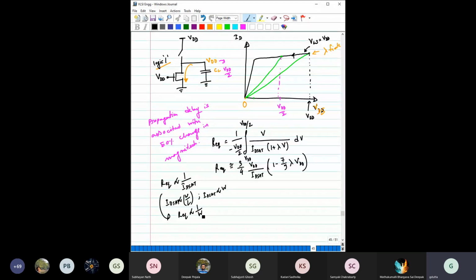So remember this relationship. If you increase W, the width of the transistor, this resistance will decrease proportionately. So suppose you need to change the resistance of some transistor for a different application, then you should be able to correlate the relation between the resistance offered by this transistor and its width.